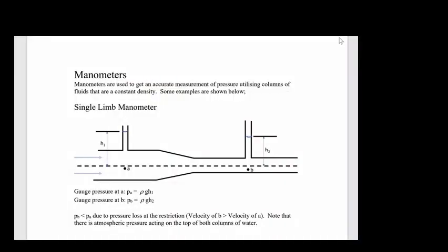Okay, so that's the plan. We'll have a look at manometers and then we'll move on and have a look at pitot tubes. So manometers are used to measure the fluid flow through a pipe. We saw in the last video, looking at Bernoulli's equation, that pressure and velocity and also potential energy are linked from one point to the next, and we can assume that that is constant if there is very little or zero energy loss due to friction and turbulent flow and so on.